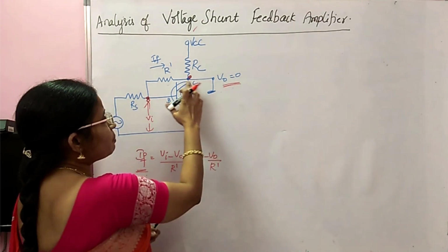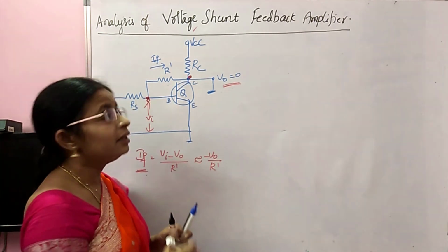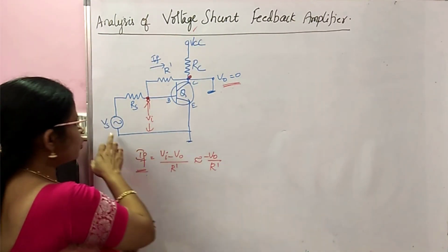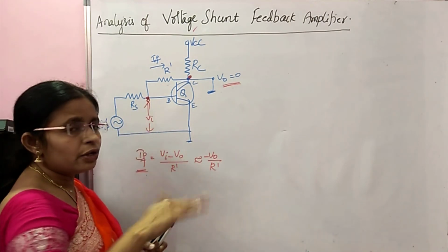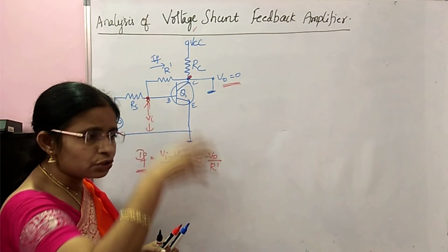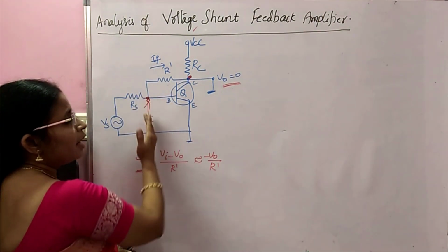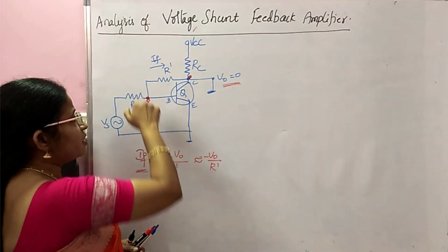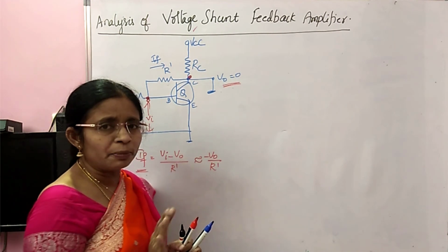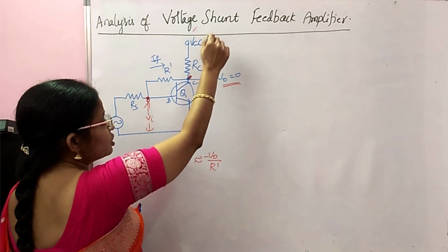As the feedback is added to the external signal in shunt as current, this mixing is called shunt mixing. Suppose you convert Vs Rs into Is Rs using source transformation, then Is and Rs are in parallel, and the current If is added at this node. Hence this is said to be shunt mixing. So totally it is voltage sampling and shunt mixing.